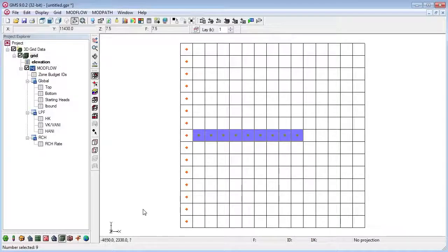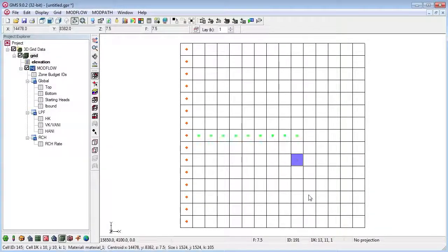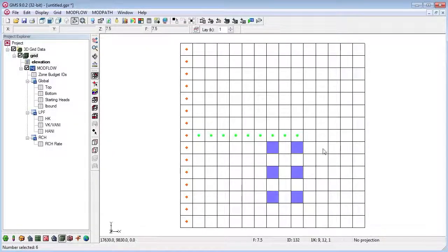Then click OK, and the drains are done. Next, we've got the wells. To set up the wells, we're going to use the Shift key again. So click the cell just before your last drain, and that should be 910.1. The IJK is 910.1. Then hold Shift and select every other.